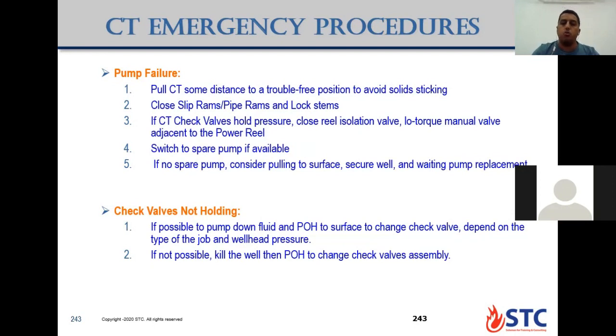Second option here is to kill the well, and usually killing the well is part of the contingency or emergency plan. You need to have kill fluid on the well site, stored and mixed inside two or three frac tanks, in enough volume to kill the total volume of the well.